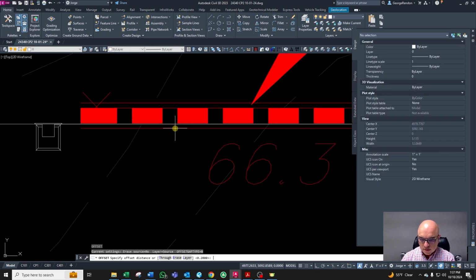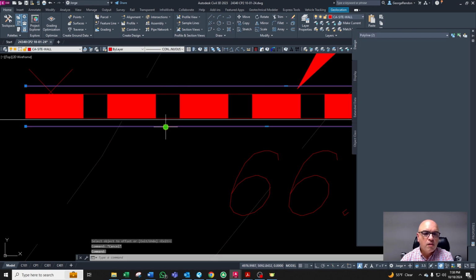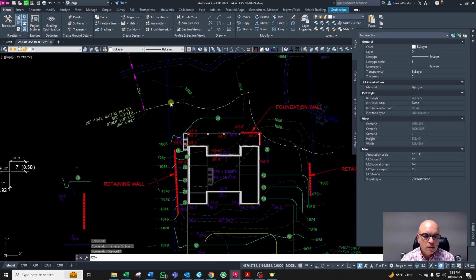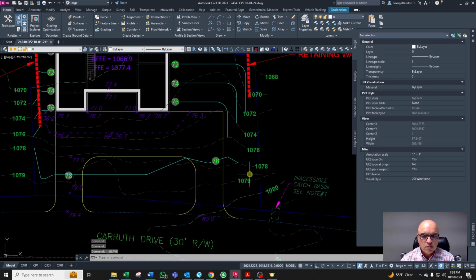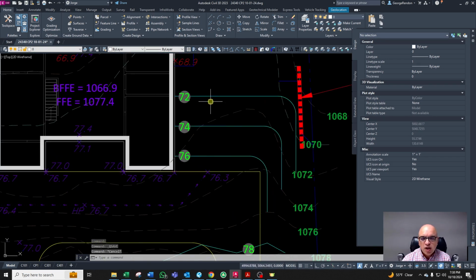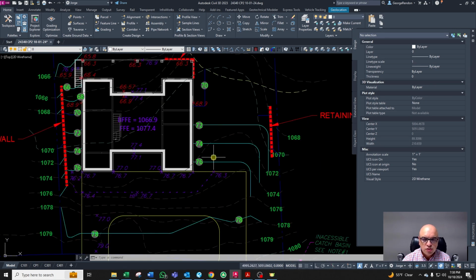I mean, if you want to, we can create a swale right here. I don't think it is needed. Basically, what we need to do is we can provide some kind of riprap along here to make sure that this water doesn't erode this slope.